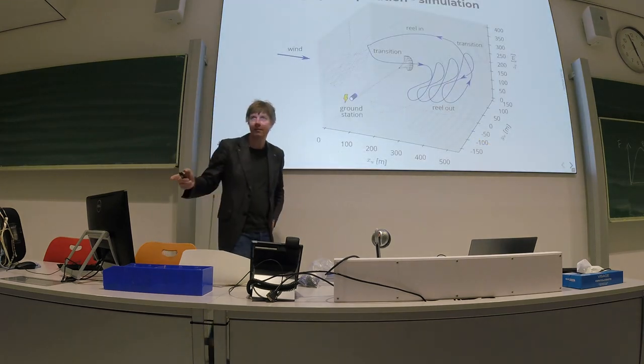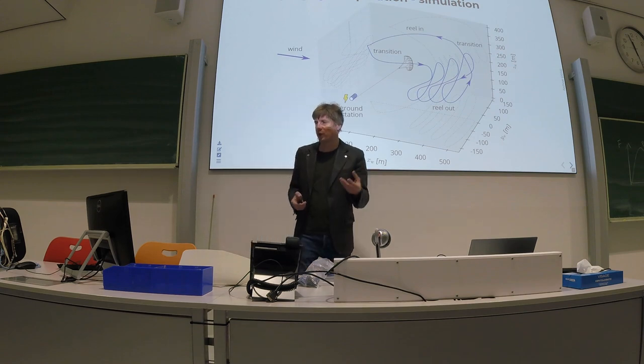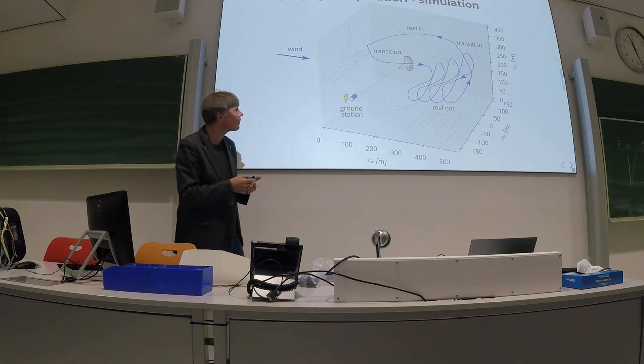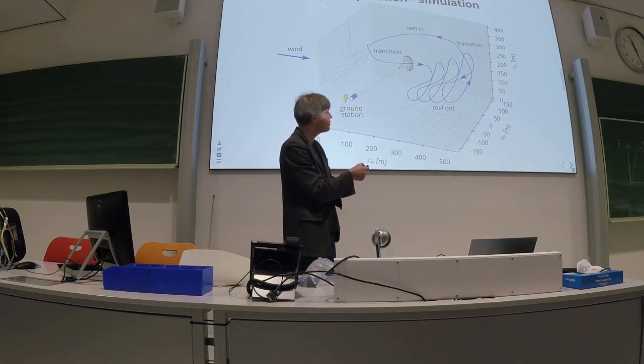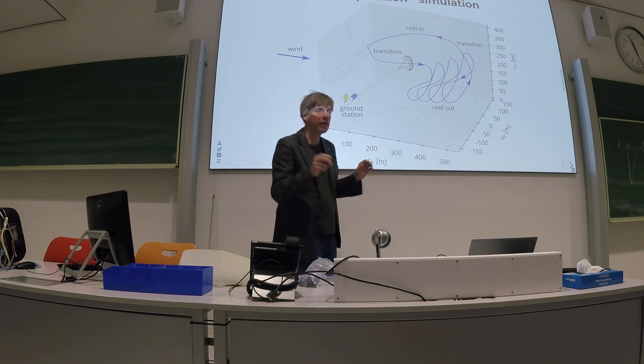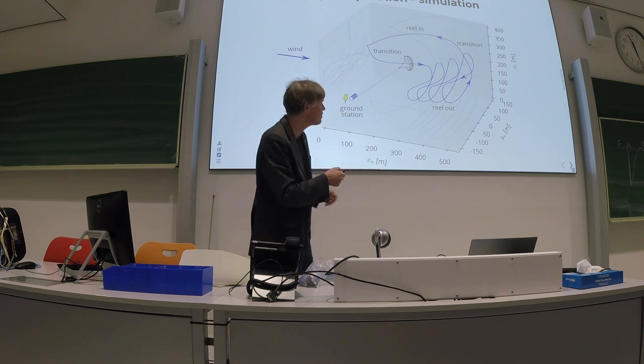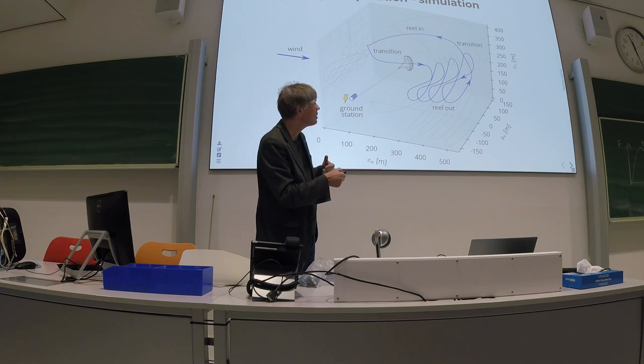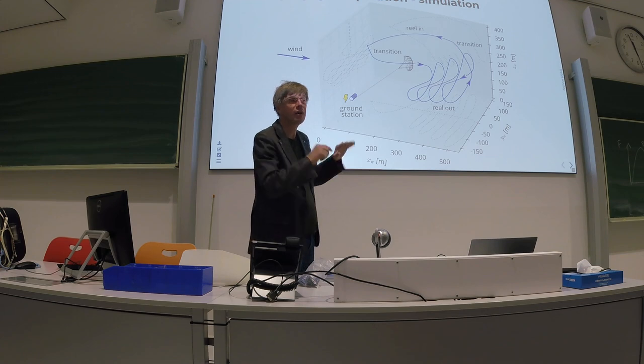beforehand. That's how the simulation would look if you would plot the entire trajectory. And this, what you see here, is the two-stage reel-in, or a two-stage phase, where we first have a transition where the kite has not been reeled in, but just once we stop the pulling phase, the reel-out phase, we point the kite upwards and it just flies to here without any propulsion.